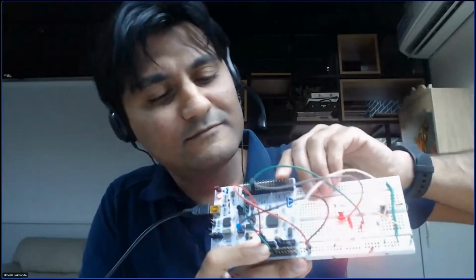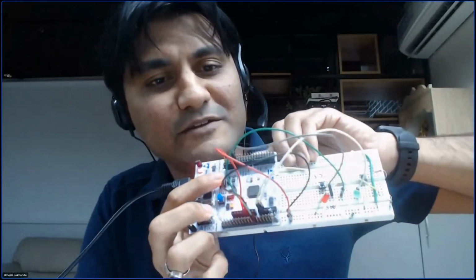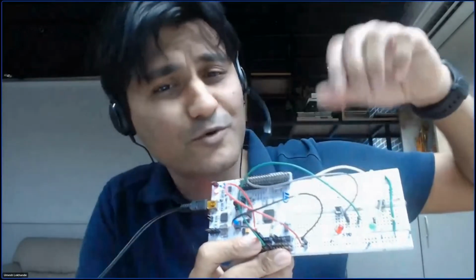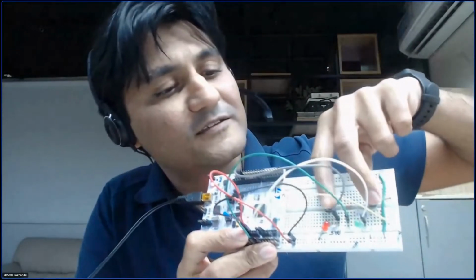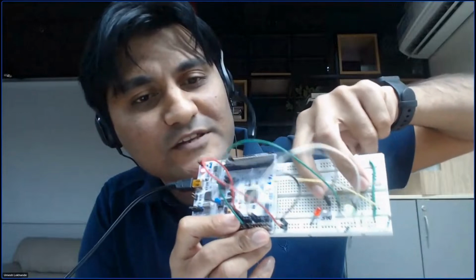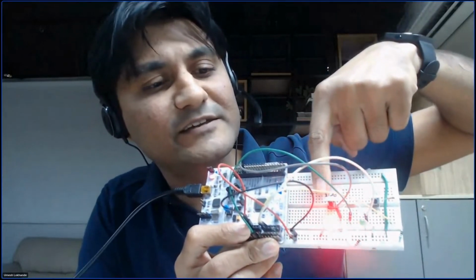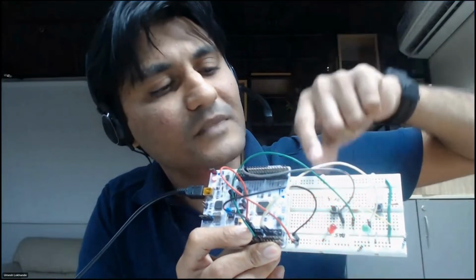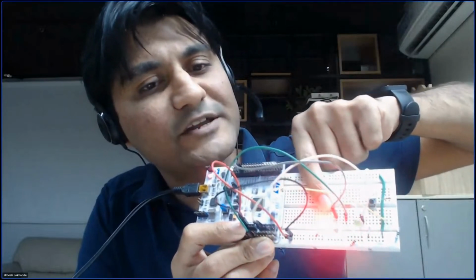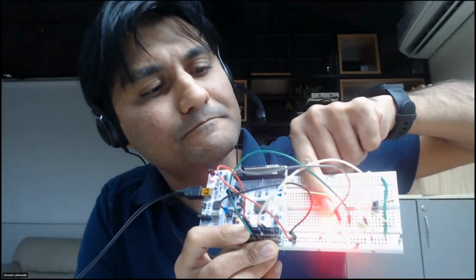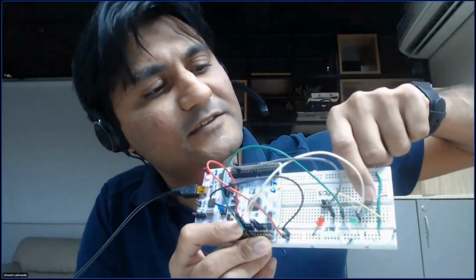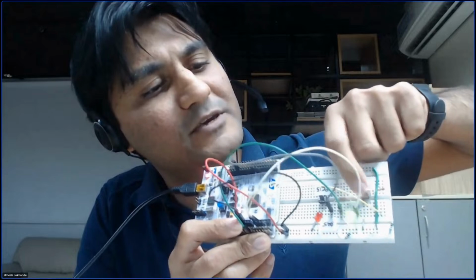I hope this gets across what I mean, right? Let me reset again just to show you because this is very interesting. So I press both buttons, so both interrupts get fired. And now you see the LED is blinking, the red LED, which has the highest priority. The moment I stop the high priority interrupt, oh, I think this button has a debounce issue maybe.